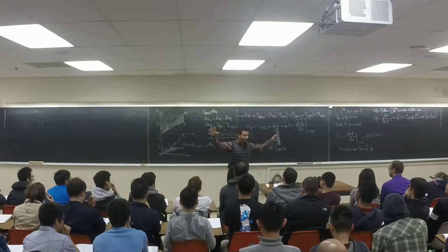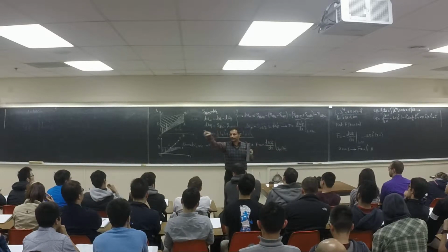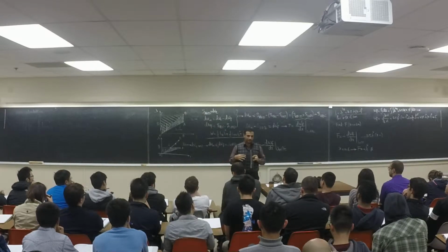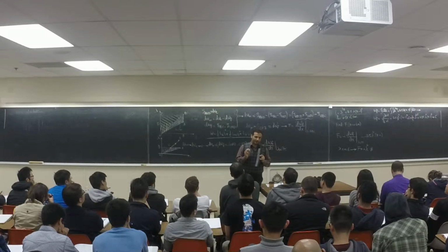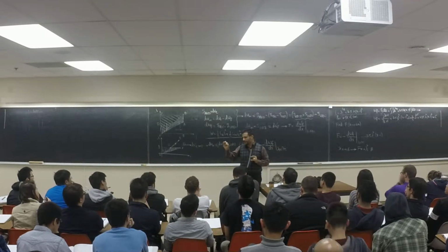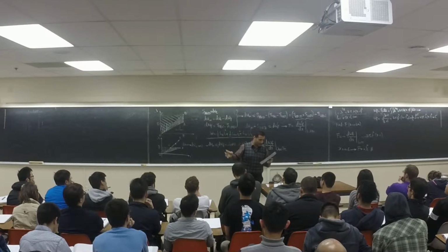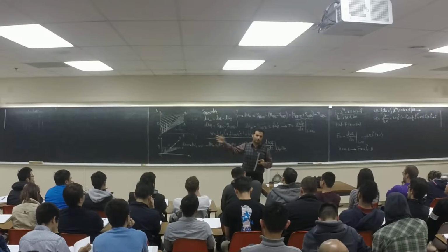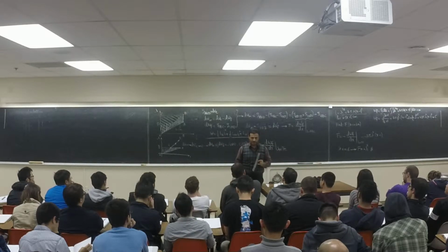But if you look at the overall system, it is not, because the VH curve is like this. But by using this technique, they make it linear. They calculate the energy or co-energy on each element, and after that they add all of them together. So now I know how much the energy is, I take its derivative, and this is the force.